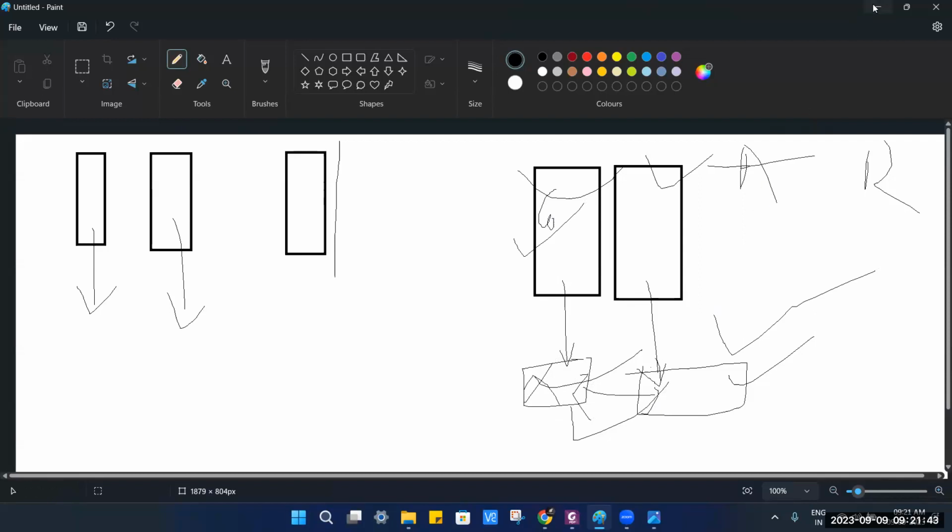In automotive, for example, if I'm building an OBD stack, I'm running a current task where I am developing an OBD stack for STM32 F407. So I am taking an Arduino example and trying to rewrite the whole thing. That PID, the CAN modes, those fields are there. Just I need to read OBD data. So that should be fairly simple. For that, you can do it simply with Cortex M. You don't need Cortex R.